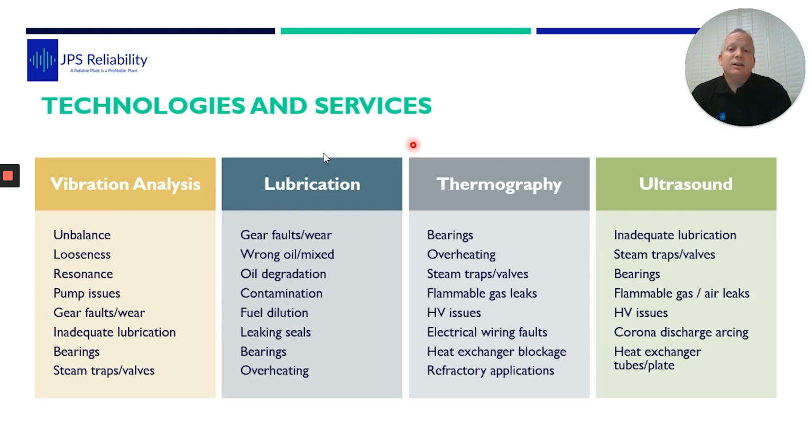Again, here's a great slide which shows that we don't just use vibration analysis or lubrication or ultrasound. We use them all. Each particular technique, for a particular failure and a particular application, can be an indicator. So it can indicate it's failed before the system functionally fails, or it can be a predictor. In this case, it was an indicator, and we can predict now, because we know what the level is, and we can now trend it. Also, it shows ultrasound would have been just as amazing in this situation with a high sample rate and the ultrasound waveform, and it probably would have been even clearer.